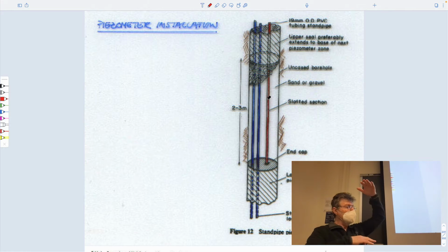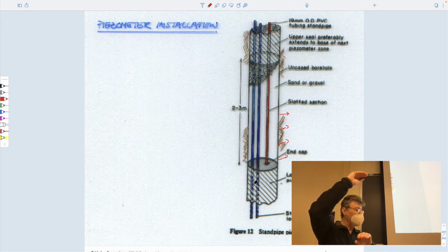It will raise the water level within the tube, and if you look at the rate at which it falls, the rate at which it falls is some measurement of the rate at which it flows out of here. And so you can use so-called slug tests, because you inject a slug of water that raises the elevation.